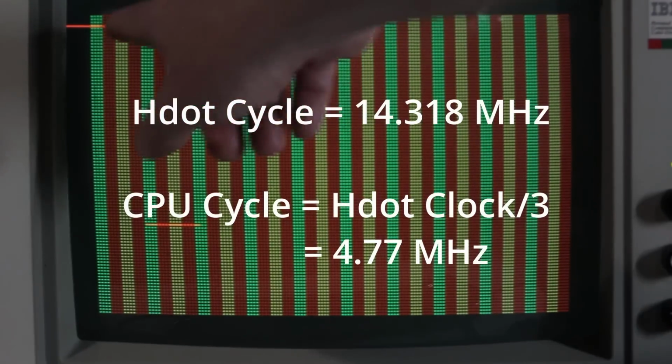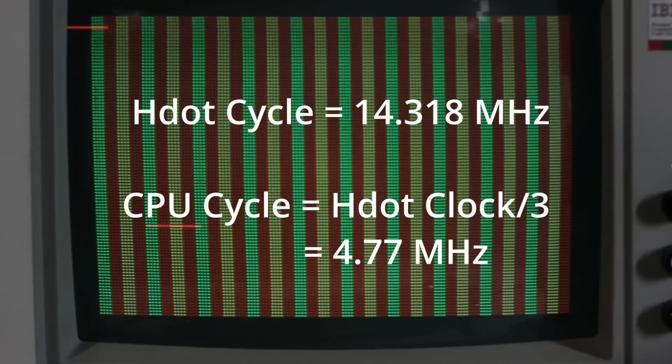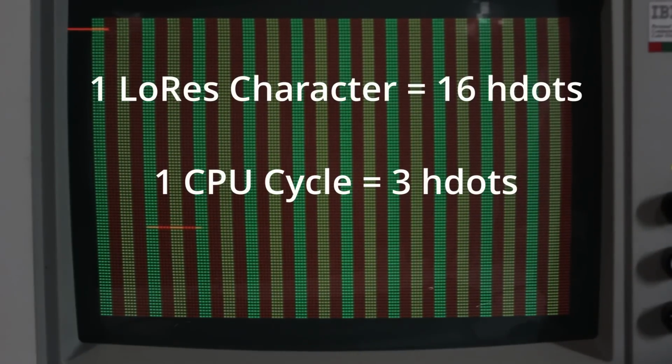The other problem is the CGA card itself runs on a clock that's 3 times faster than the CPU. We call the cycle of the CGA clock an H dot, and there are 16 H dots per character. There are 2 per pixel in this low resolution mode, and there are 3 H dots per CPU cycle.